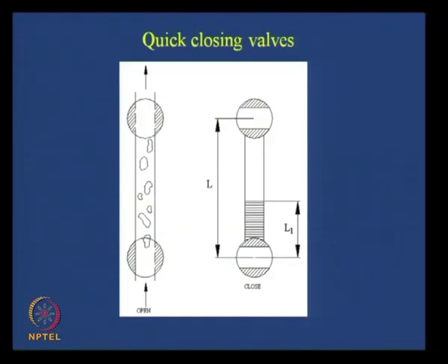The other thing, suppose it is not so very easy, the volume measurement I will tell you. The most direct way of doing it is very evident to you. A two phase mixture is going, there are two valves attached at the two ends or across a particular section of the entire test rig. They are closed simultaneously. This is a very common technique. They are closed simultaneously to arrest the two phase mixture within them.